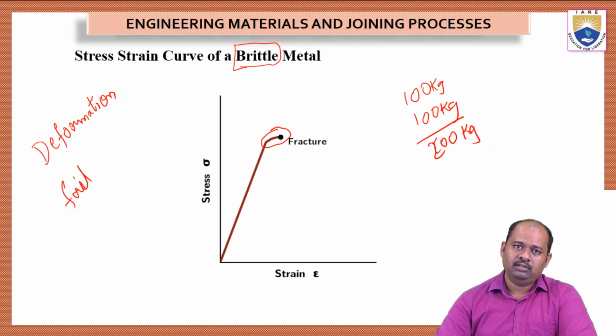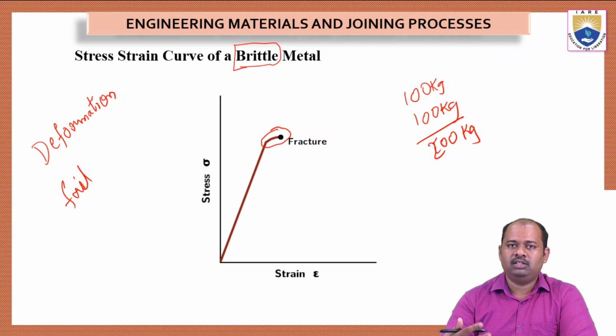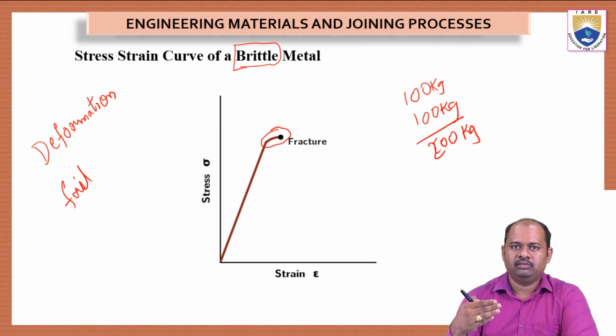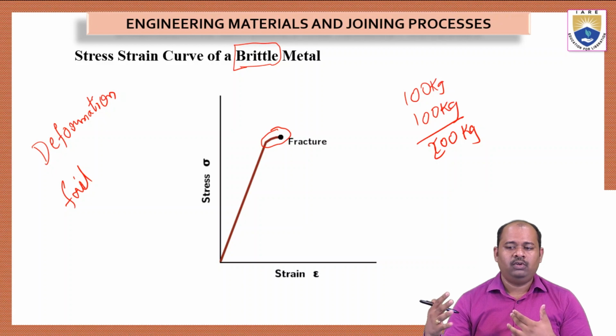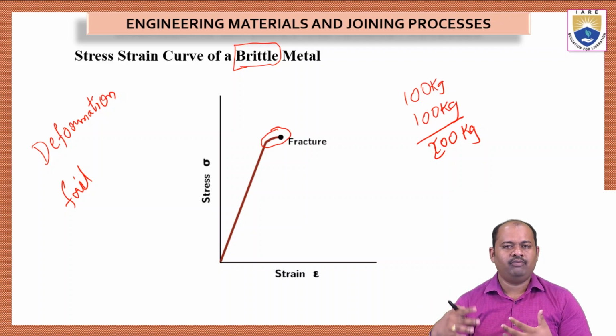Yet, the springs or the wheels, no part of the motorcycle will fail, because they are designed within the limit, within the yield strength limit. That is why they are safe, because even though the load is more than the yield strength, it can bear up to the ultimate strength point. And after ultimate strength, it will definitely be broken.